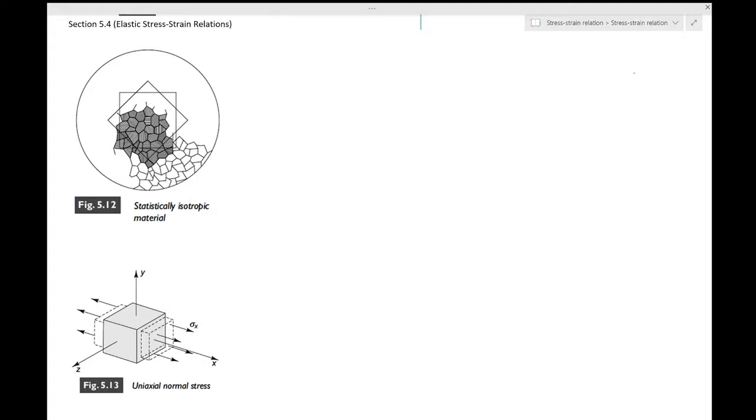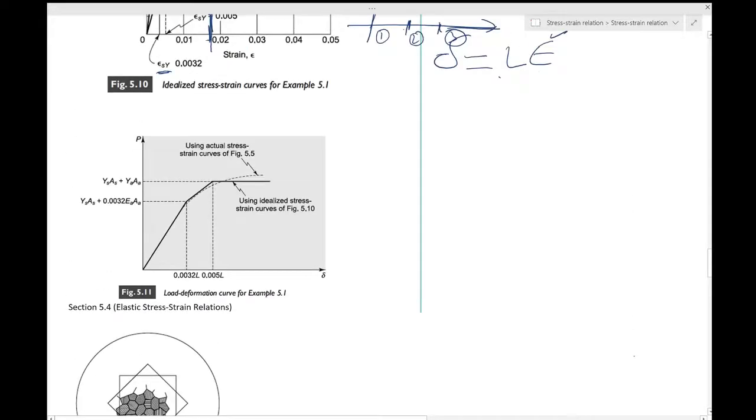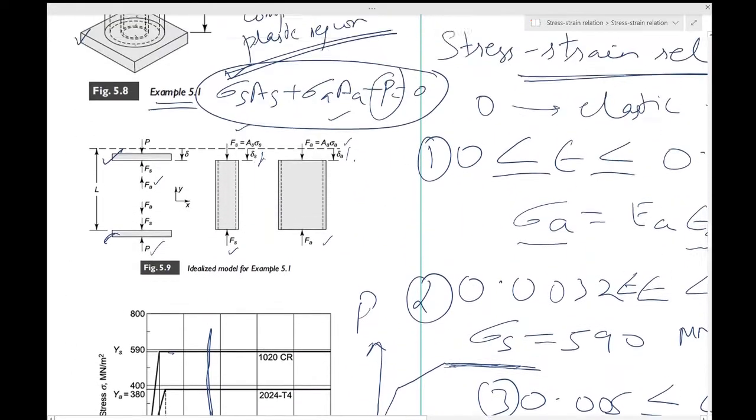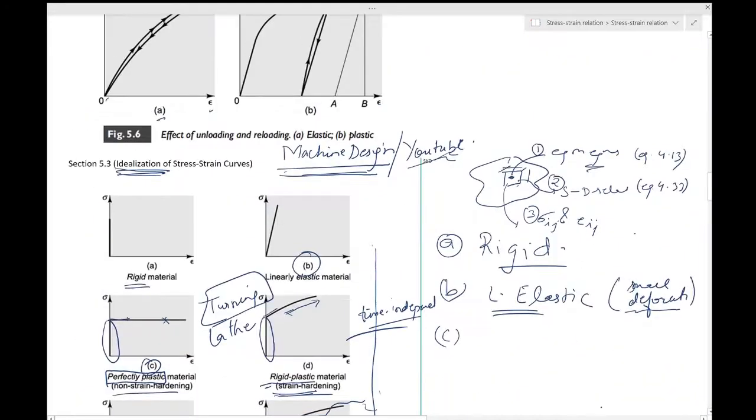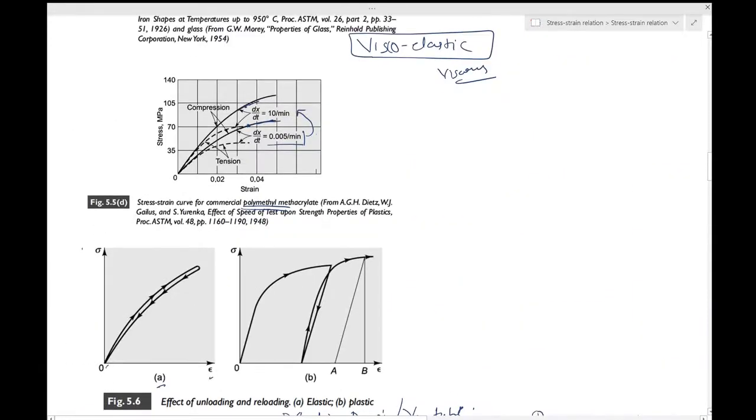Okay, so clearly when we derived these definitions of strains, we had pointed out that the strains are small compared to 1. Okay, so that is why it was a small strain theory. Okay, so this assumption of taking a linear elasticity works well for many cases, even for say steels. Okay, even for a material like steel, or metals in general, I mean.